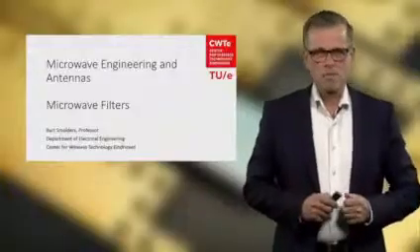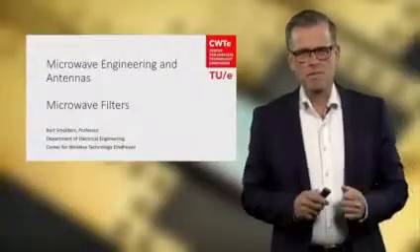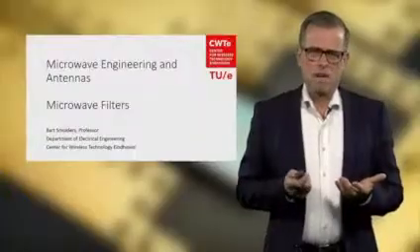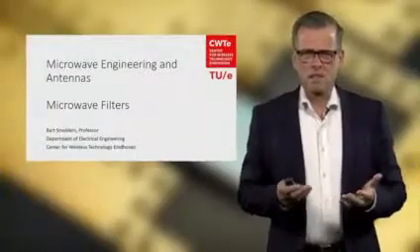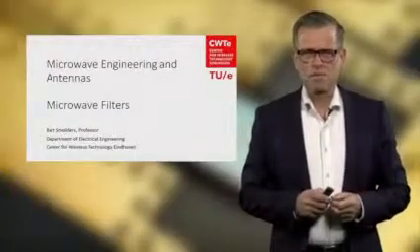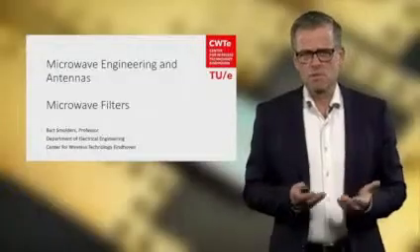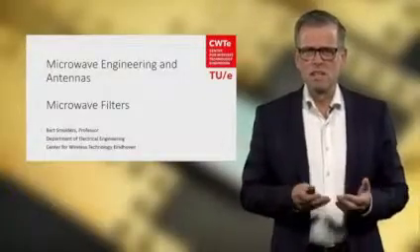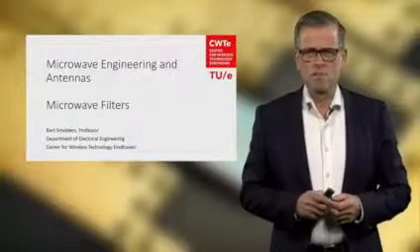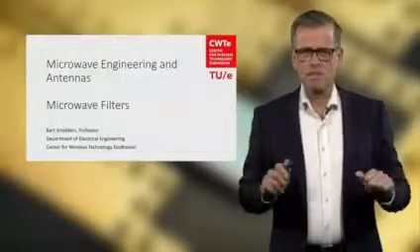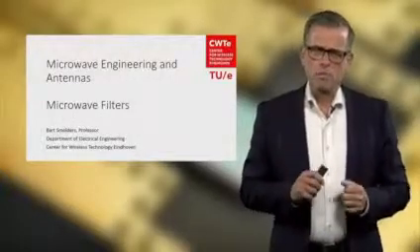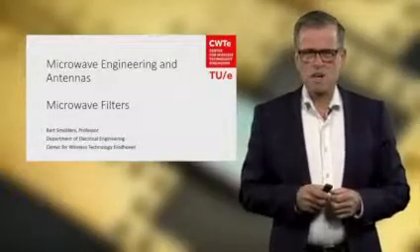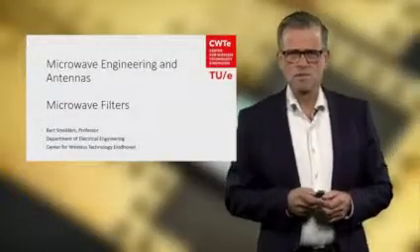Welcome to this web lecture where we're going to discuss microwave filters. Microwave filters are another application of transmission line concepts, and microwave filters are very useful. For example, they can be used in receivers to reduce the linearity requirements by suppressing out-of-band interference, or they could be used together with transmitters to suppress out-of-band spurious components that might occur.